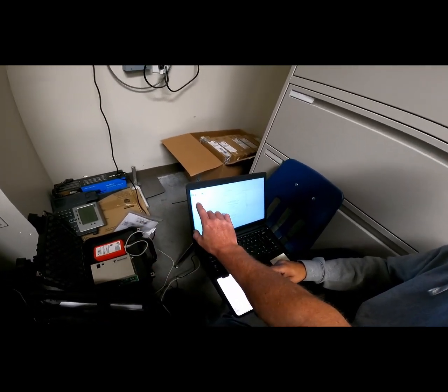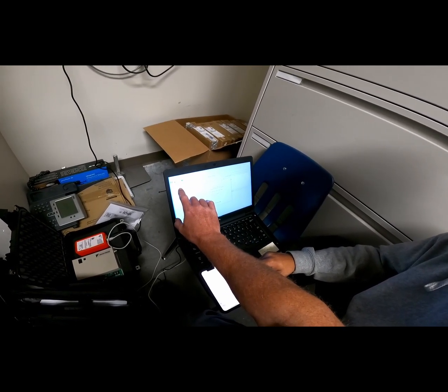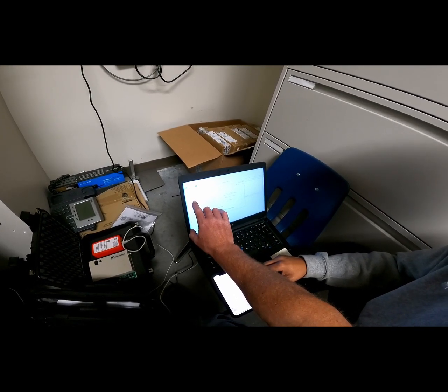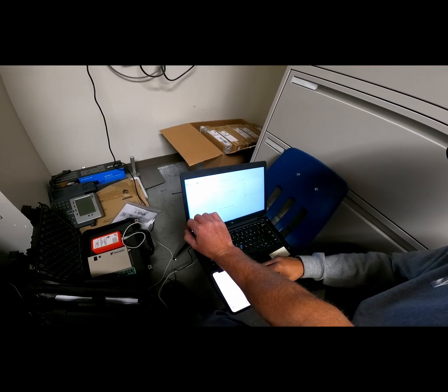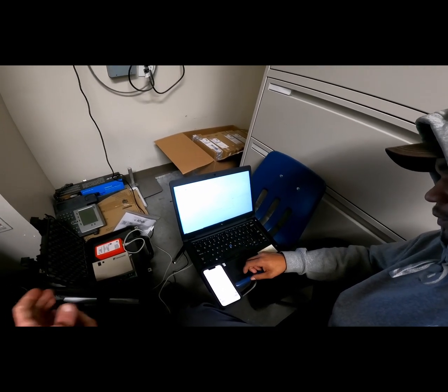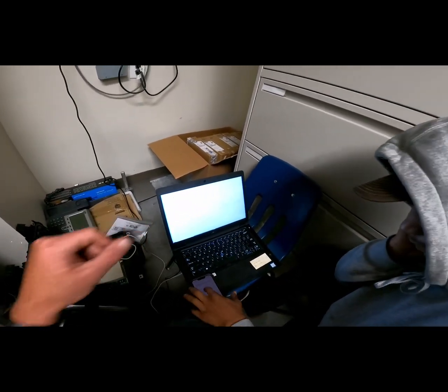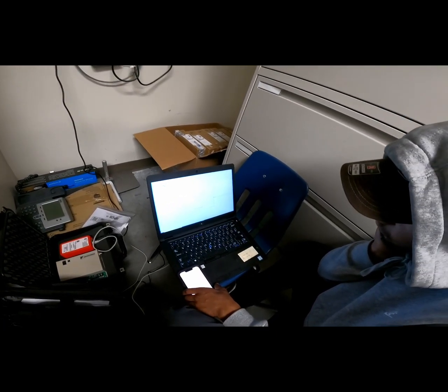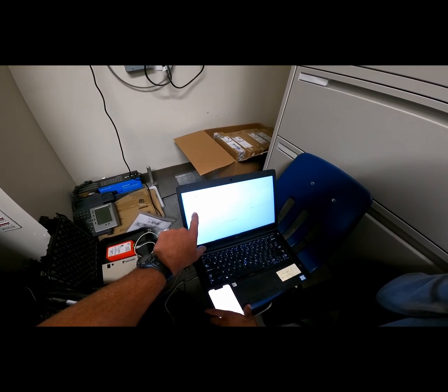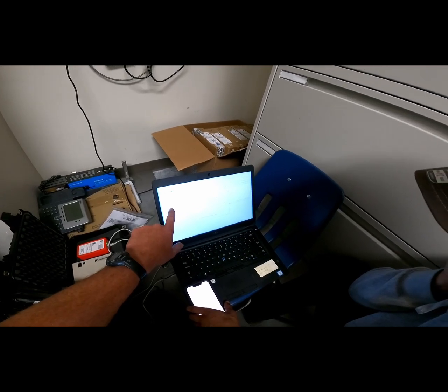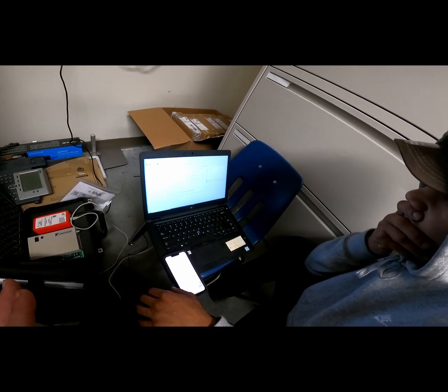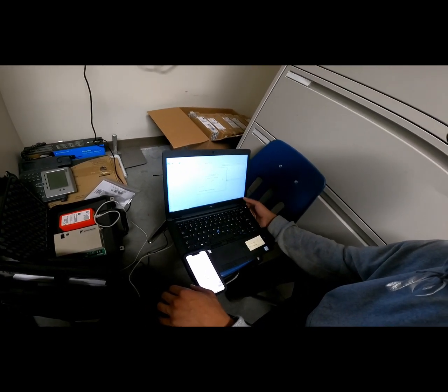The indoor units' addresses always start with 01 or 001. The outdoor units' addresses generally start at 50. But you'll have multiple outdoor units addressed, and they'll be in the 50s, the 60s, maybe even up into the hundreds, because there's 4 different systems. If there's only one outdoor unit, chances are they used address 50 for the outdoor unit and 51 for the branch controller. The branch controller is where the outdoor unit sends all its refrigerant to, and then it gets dispersed to all the indoor units from there.